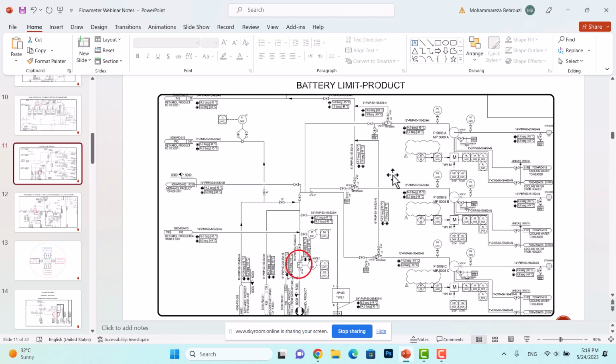And since the whole purpose of these refineries, these chemical and petrochemical process plants is the products, and since we want to sell our products with the highest profits, we should be very meticulous, very careful with the flow rate of the products, because it is extremely expensive and we want to make more money. In order to avoid such financial consequences, we have to select the best type of flow meters, which is Coriolis flow meters for these applications. So we select Coriolis flow meters for products.